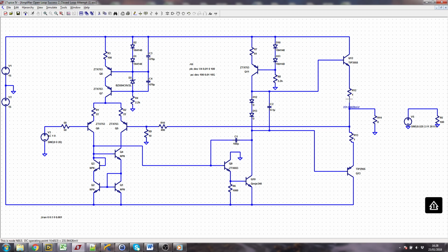These are quite big. They're quite big because we really only want them to pass a large current through here, and we get a voltage drop here which acts to switch off this transistor a little bit, just in case the situation arises. This transistor got very hot. You've got a VBE here. IC will increase because the transistor is hot, which makes the transistor hotter. So for a given VBE, because it's got hotter, the IC will go up a bit, which makes it even hotter still. And of course eventually it will blow up.